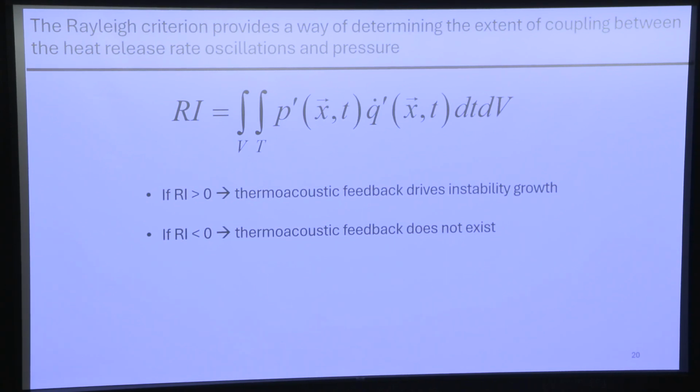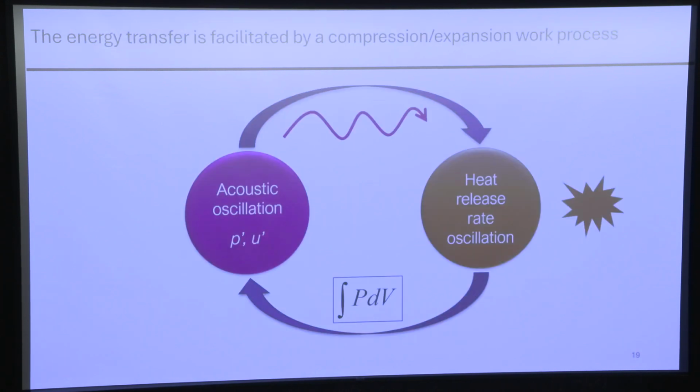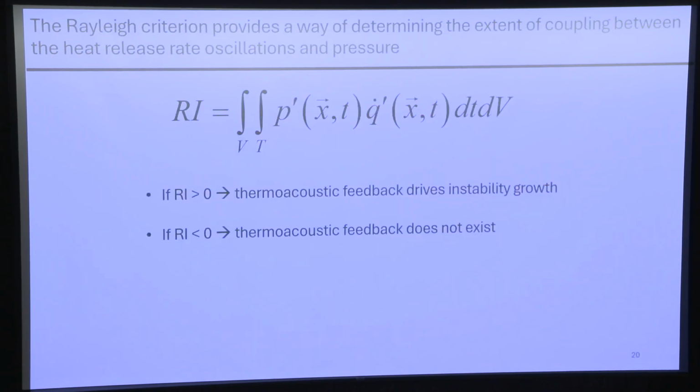One of the things he talked about, he did not know that this was going to be a problem in rockets, but one of the things he talked about was this potential coupling between heat and sound. And so he basically says that it's possible, right? He derived this, and so you'll find the name Rayleigh shows up in a lot of thermoacoustics as a result. And so the Rayleigh index is this equation right here.